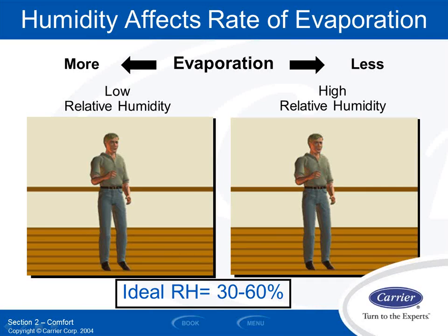60% maximum in many cases not only is for comfort, right, which is where ASHRAE standard 55 comes in, but it's also for controlling certain types of organisms, specifically mold. If you are at about 70% moisture for about 2 weeks or so, you're probably going to be able to grow mold. And if you're at 80% moisture, it'll probably take about 3 days to start growing mold on surfaces, right? Mold needs several different things to grow.